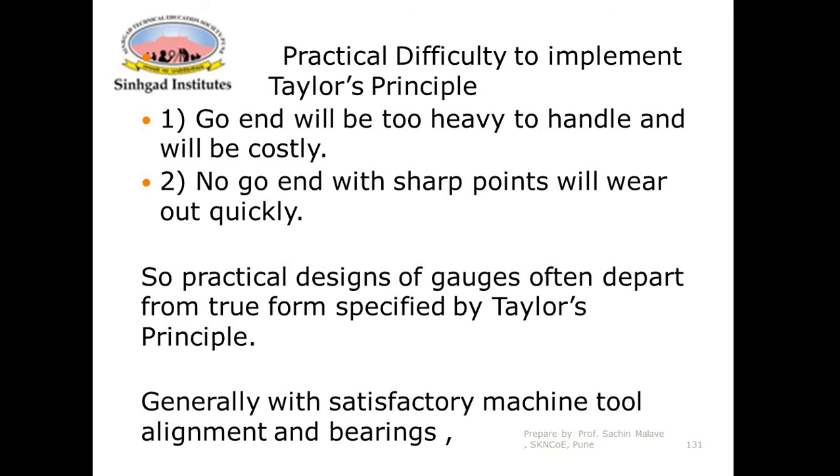Just imagine, to check the size of this component, you have to make the go end whose diameter is 1 meter and its length is 500 mm. See how big the go end will be. That will be too heavy, you cannot handle it. It is very difficult to handle and it will be costly also.